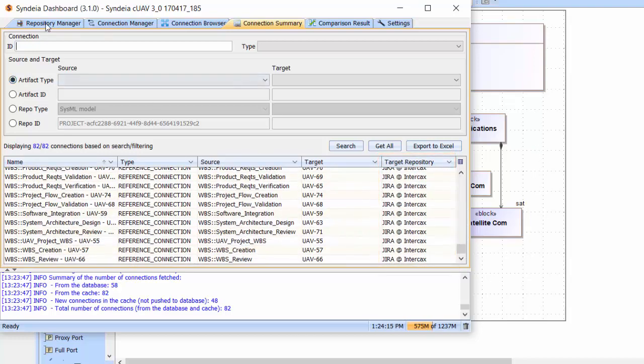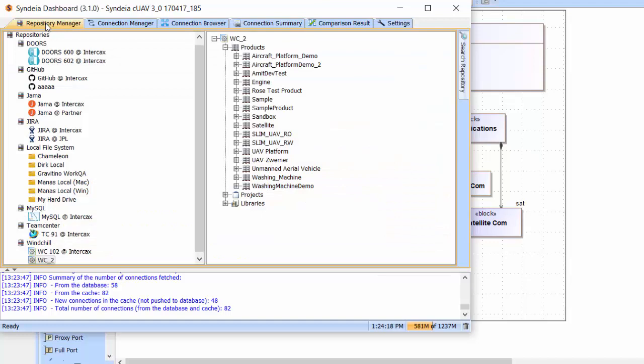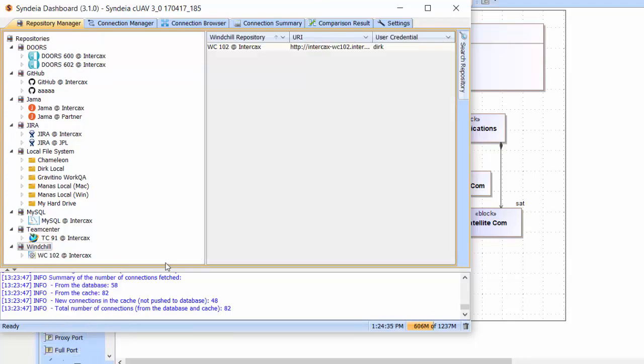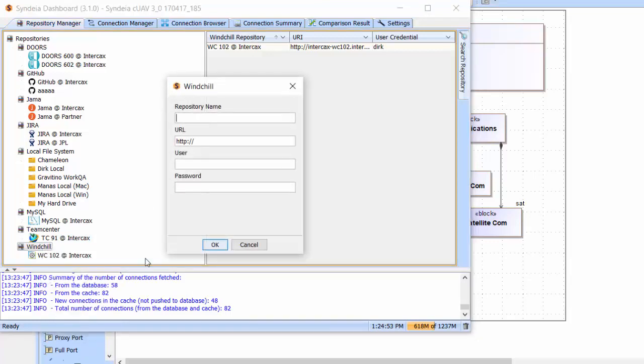Once created, the repository connection cannot be edited. If it is necessary to change the URL, username, or password, it is possible to delete the existing connection by right-clicking it and choosing Remove. Be careful if you do this in database mode. Others may be using that connection. You can restore the links by adding a new repository connection and keeping the original name. The model connections created under the original name will still be valid.